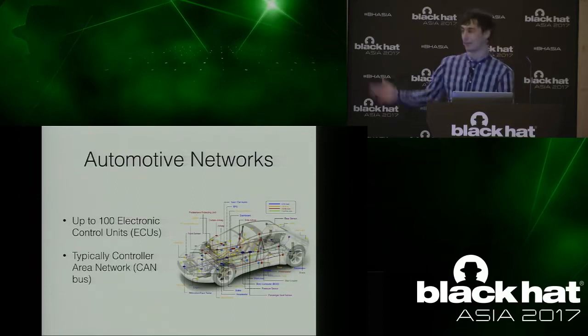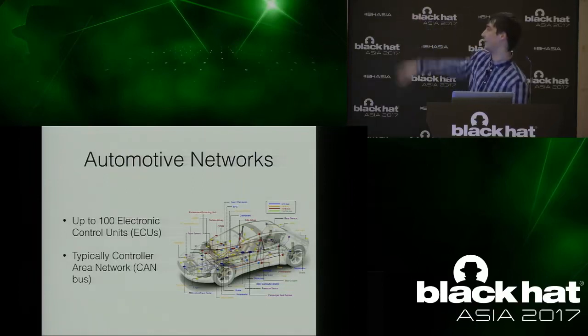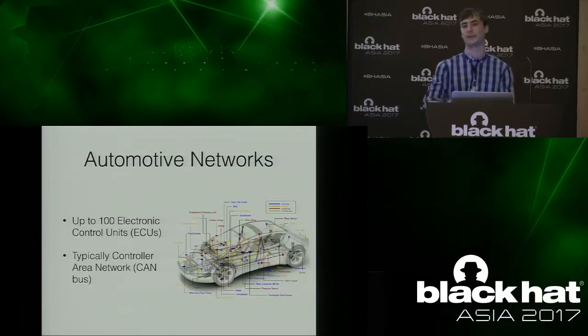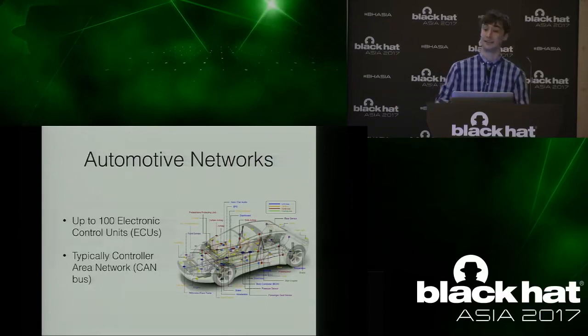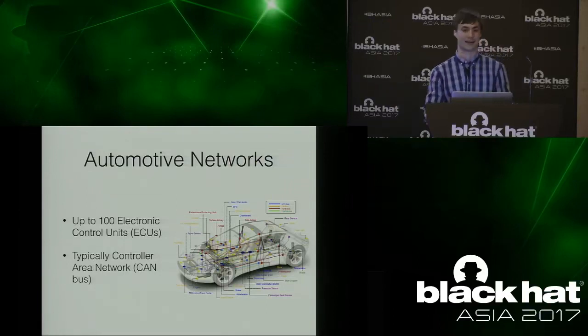And yeah, a modern car might look like that with all these different units floating around inside of it, and they can all be on different CAN buses, and then those buses might be bridged by different ECUs that act as gateways, so you get a very complex network inside every single vehicle.